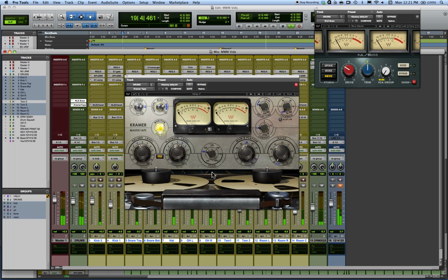The next is the flux circuitry, and this is where we get into the different forms of tape machine alignment. This is actually an internal adjustment and it's part of the tape machine alignment. So the level meter will not change, but you're applying more saturation to the tape internally. The idea is that your input level is setting what the VU meter is showing you, and the flux is determining based off of that level how much you're saturating the tape.